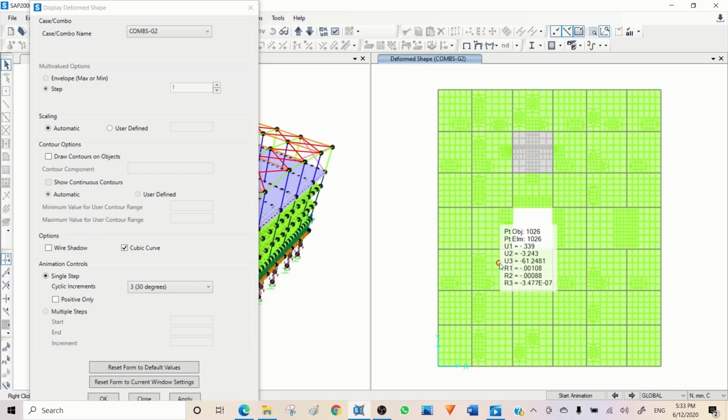What is important to check the slab is you need to check the slab deflection based on local displacement, considering the supports are fixed, and you should ignore the displacement of the support. So 51 millimeter is already the displacement of the column here. So that shouldn't be taken into account to calculate the displacement or deflection of the slab. So deflection of the slab here is relative to the supports.